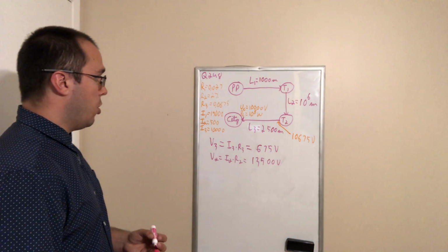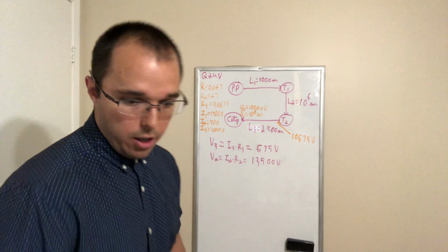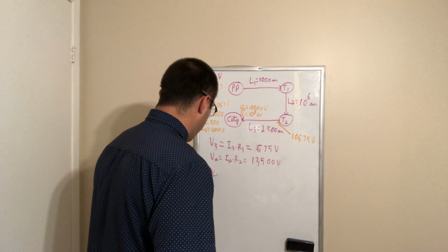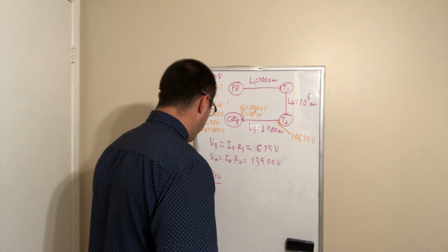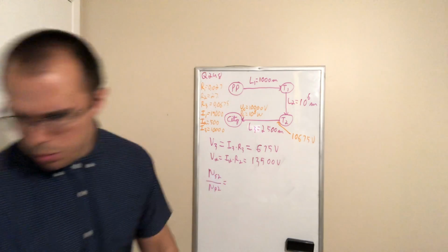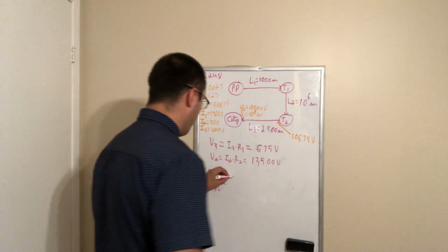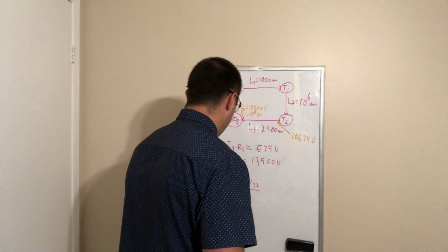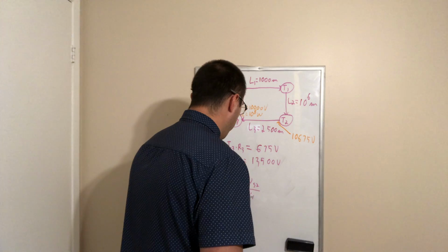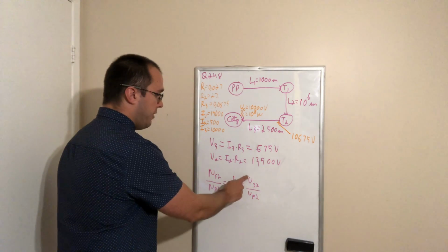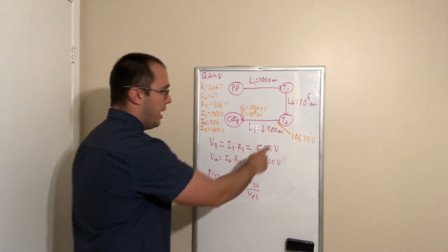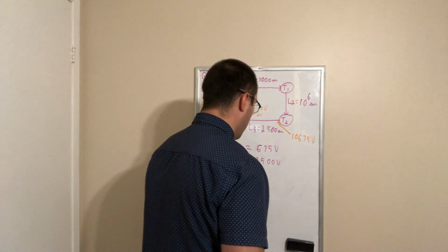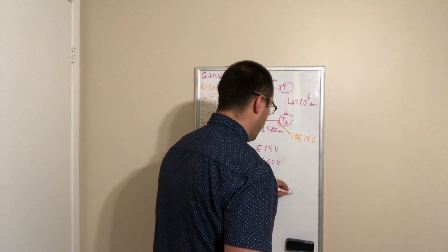All right, so let's go back to the formula for our second transformer. We got NS2 divided by NP2 is equal to 1 divided by 20. This is equal to VS2 divided by VP2. And we already found VS2. It is the voltage at the exit of the second transformer. It's 10,675 volt.